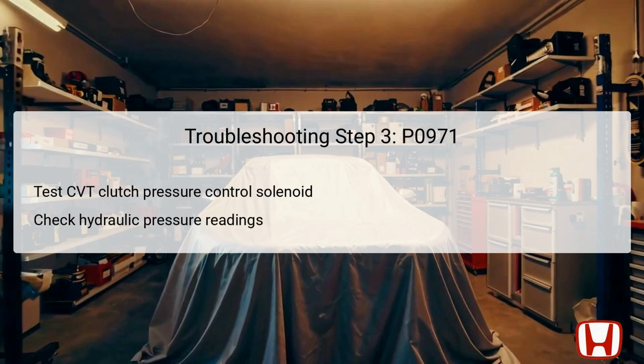In the third troubleshooting step, direct testing of the CVT clutch pressure control solenoid is required. Utilizing the HDS, the technician should engage the solenoid while monitoring its performance. The solenoid should respond appropriately to the commands given, adjusting hydraulic pressure as indicated by the readings on the diagnostic tool. Additionally, verifying hydraulic pressure readings is essential to confirm that the solenoid is functioning within specified limits.